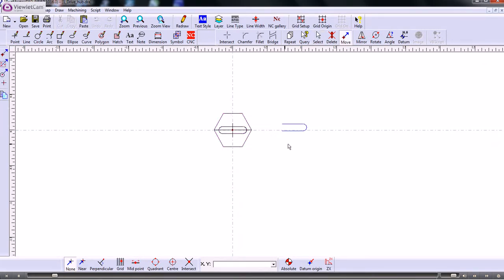Now the problem with that is that until you cut and paste it, you don't know where the hook point or the reference point in the selection is, and that reference point can change depending on how the geometry was created, when it was created even, what sort of iterations have gone through deleting items, replacing items, etc.